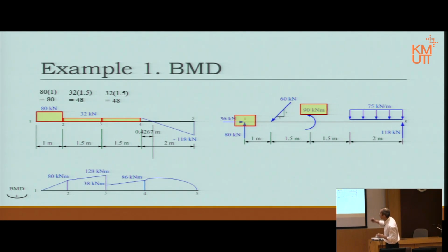Notice the slope. At point 4, the slope is positively high, and then it reduces. So the curvature increases quickly and then slowly, and becomes a peak where the slope cuts 0, or the shear cuts 0, the same point. After that, the slope reduces slowly, and then at the end reduces quickly. Therefore, it becomes that shape.